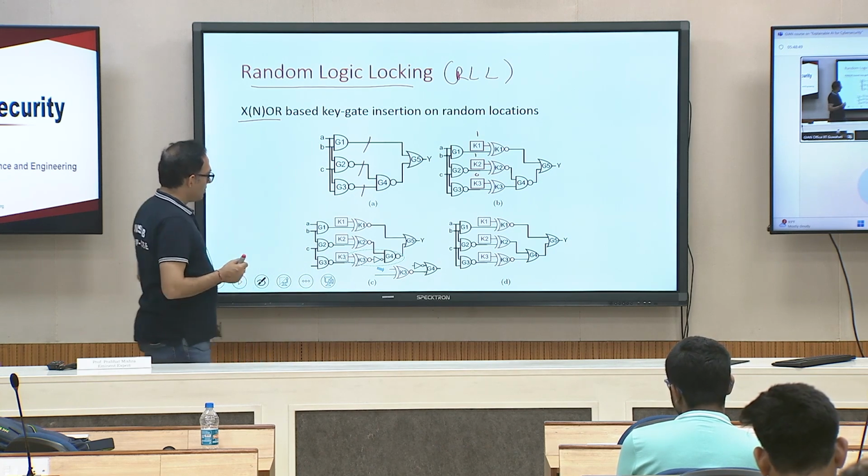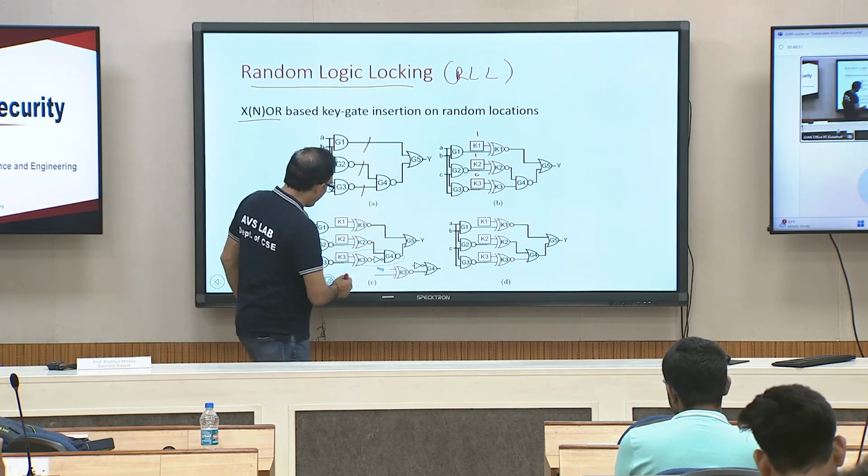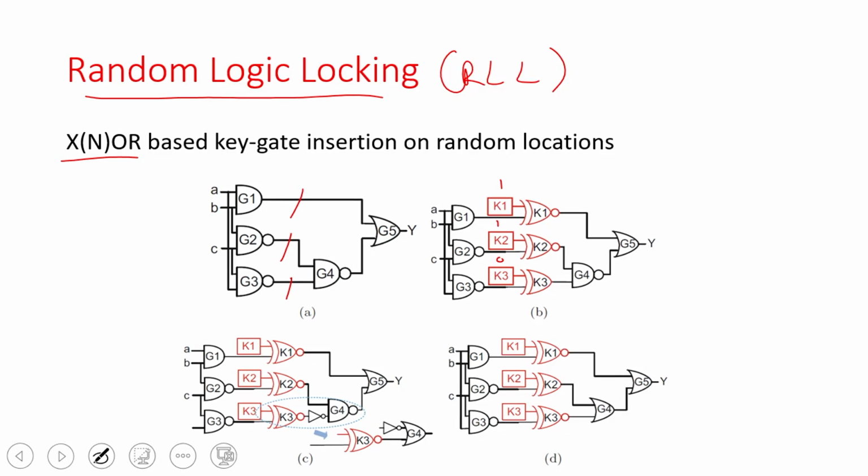What will I do? So, I already have this one, which is an XOR gate. What can I do? I can put two NOT gates here, right. So, this becomes an XNOR gate now, and these two NOT gates I can move here, right. So, I can basically put bubbles around this XOR or XNOR gate and I move these bubbles, or the NOT gates.